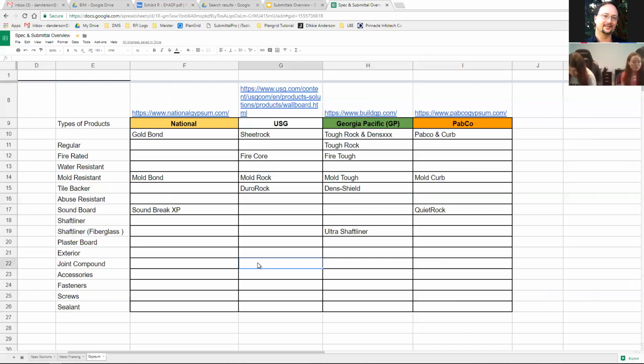The challenge is it doesn't sand and it doesn't finish the look of it. It doesn't remain consistent because it has different chemicals in it, so it will dry differently. It will create different marks inside the compound than anything else. And that's the 90 and 60 mud you said? Yeah, all hot mud, or 10-minute, 30-minute, 40-minute, whatever minute hot mud there is, that is used as a patching type of mud. Oh, I just need to do a patch. I need to get in and get out and get it done quickly. You would use it as that.